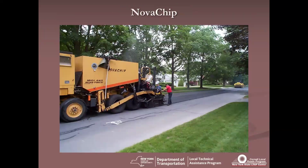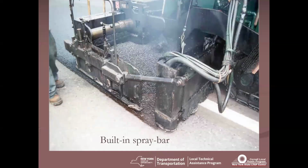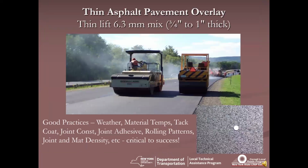Nova Chip is a hybrid operation. It's a chip seal on steroids, and the key here is you're using your polymer modified asphalt mix. But the key is you've got a built-in spray bar that's putting down a real thick polymerized tack coat. And this is truly what we would call an armor coating application. And then our thin asphalt overlays, that's our standard 6-3 mix. It's up to an inch thick at DOT. Key here is you've got to follow your key paving good practices.